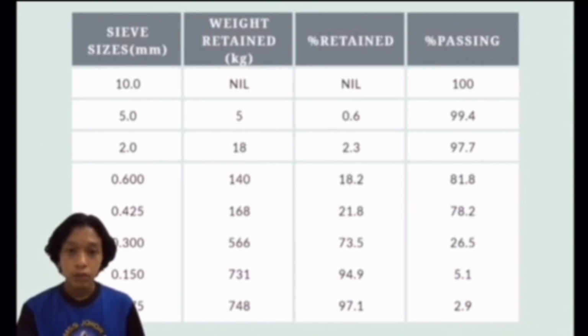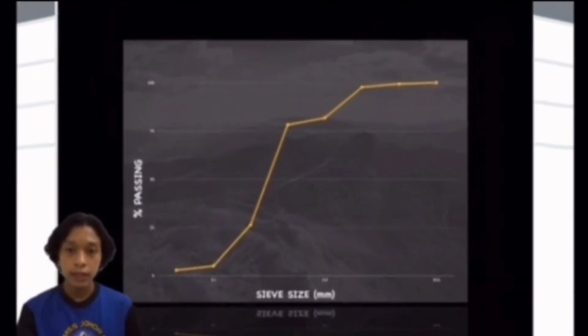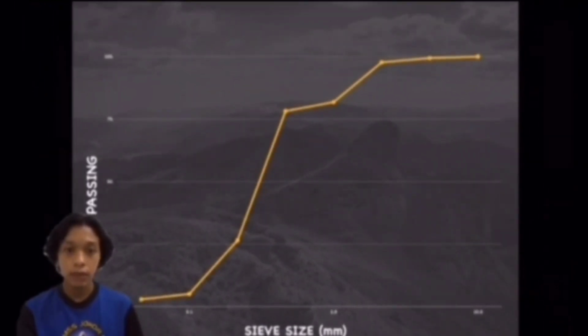The result should be calculated and reported as the cumulative percentage by weight of the total sample, then the percentage by weight of the total sample passing through one sieve and retained on the next smaller sieve, to the nearest 0.1%. The result of the sieve analysis may be recorded graphically to get good quality aggregates.